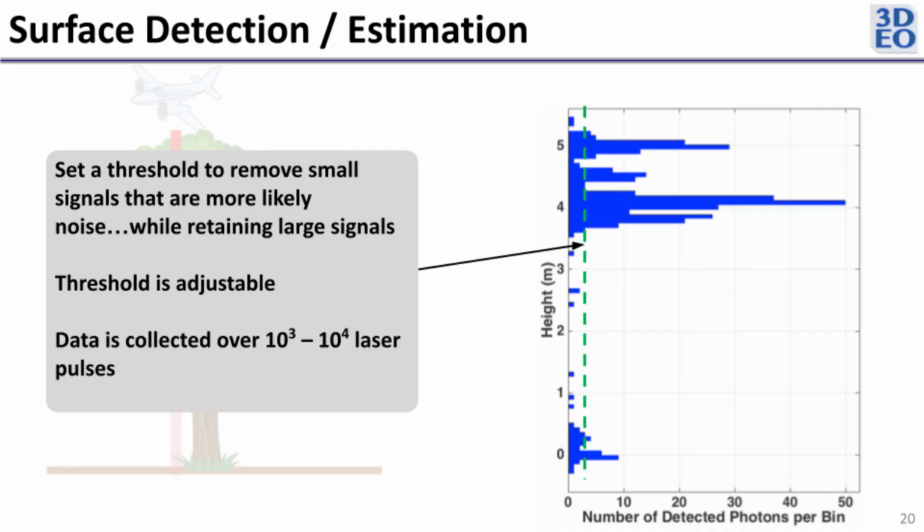This is different because on one laser pulse, our signals are very, very low, but we aggregate them together from all the different viewpoints, and at the end of the day, after we've aggregated, we ask, does this exceed the threshold? So it's a different way of doing it, and it allows us to detect these very weak signals, either from small branches or from very weakly reflected ground.